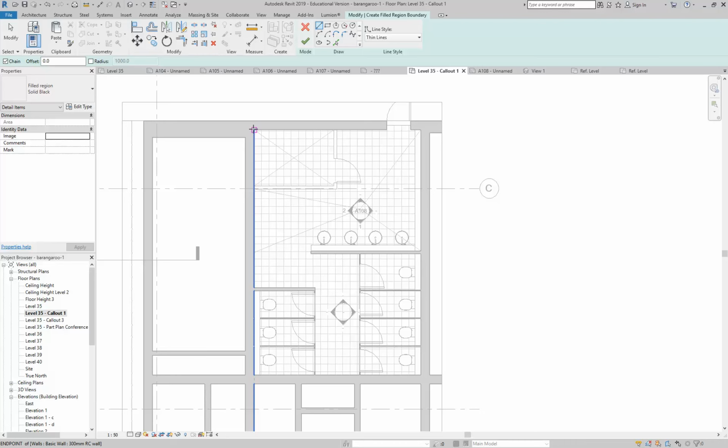Well, you can use split face, but split face is hard, and also there's a limit. It starts not working properly once you go beyond a certain number of split faces. The one I showed you at the beginning, you can do like 6 or 7, and then it seems to stop working properly. I couldn't get it to work on curves. No, it doesn't work on certain surfaces. Only sometimes. That's what I do normally. If I know I'm going to construction, which is most projects, then I'll do it exactly like that because that's how you build it.